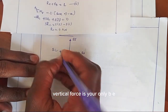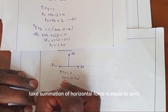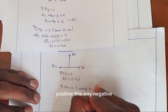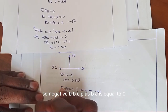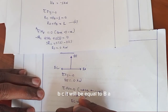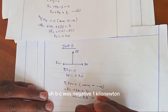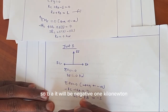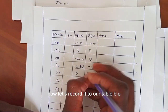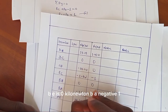Vertical force is only BE, so BE will be equal to 0 kilonewton. Also take summation of horizontal force is equal to 0. Positive this way, negative. So negative BC plus BA is equal to 0. BC will be equal to BA, and BC was negative 1 kilonewton, so BA will be negative 1 kilonewton. Now let's record it to our table. BE is 0 kilonewton, BA negative 1.